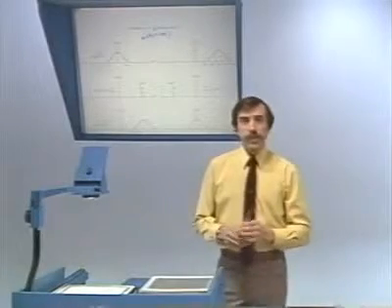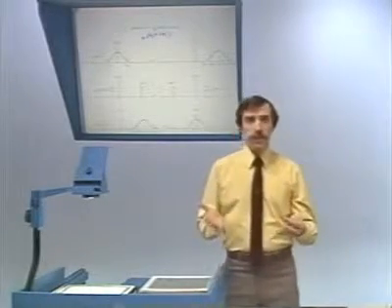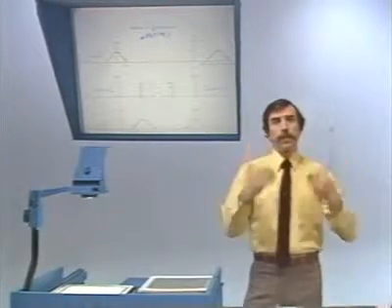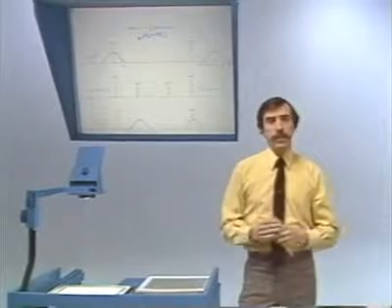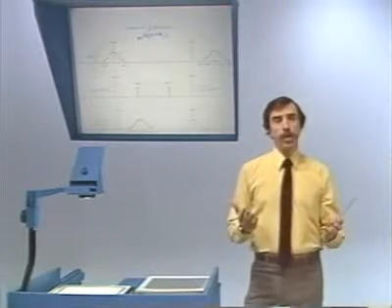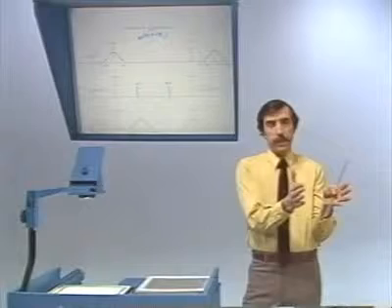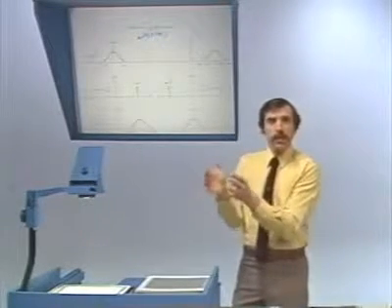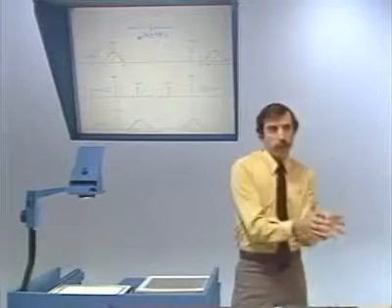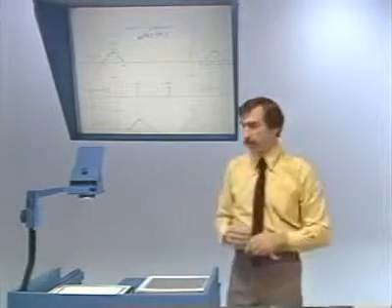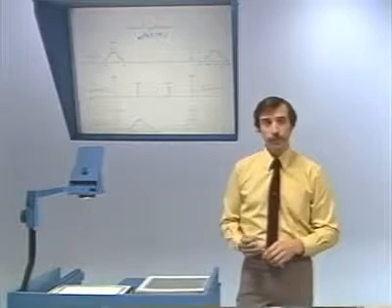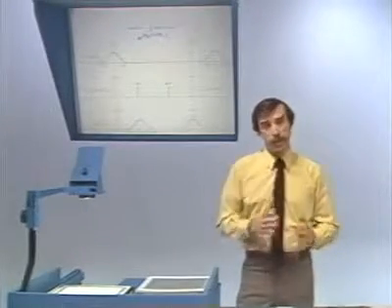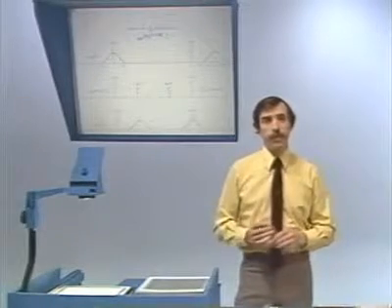So what this says is that if we have a signal, x of t, and we use it to modulate a complex exponential carrier, in the frequency domain, what we've simply done is to take the original spectrum and shift it in frequency so that what was originally at 0 frequency is now centered around the carrier frequency. We've now modulated, in effect, to a higher frequency. Things are happening in a higher frequency band.